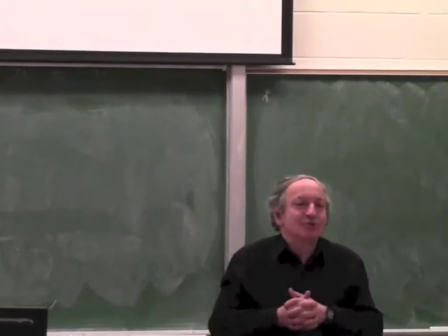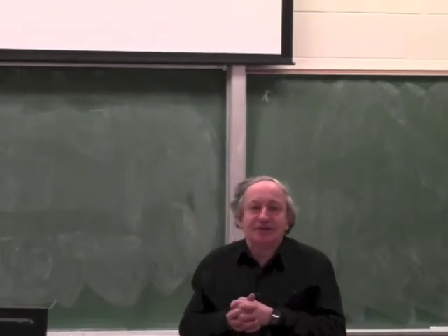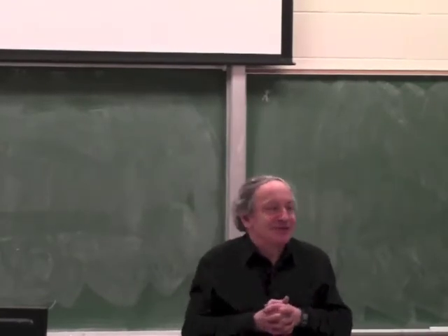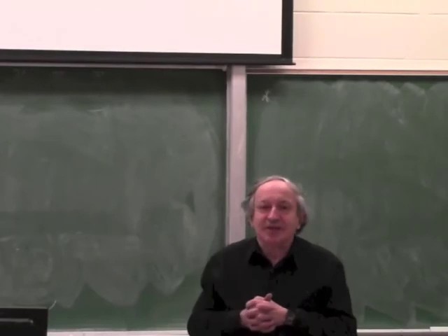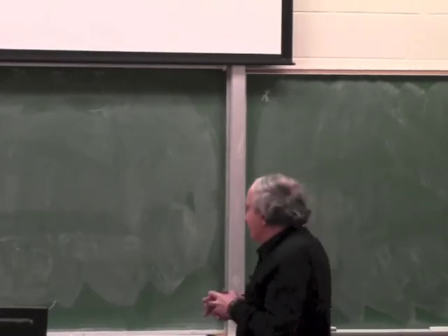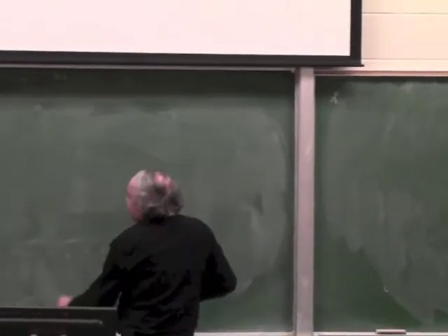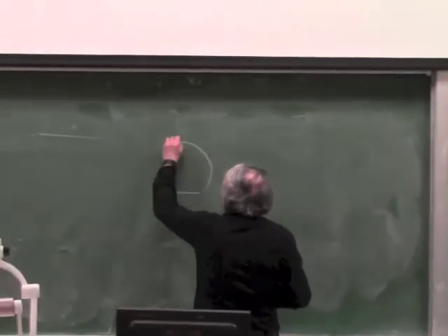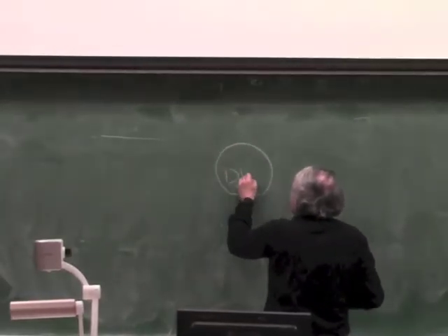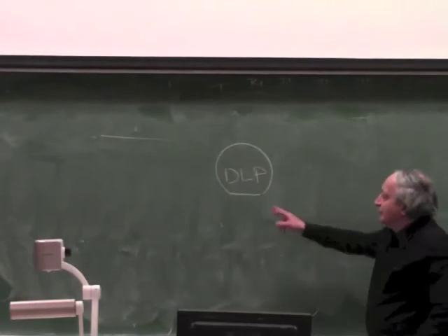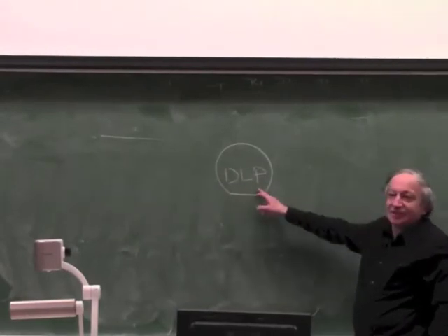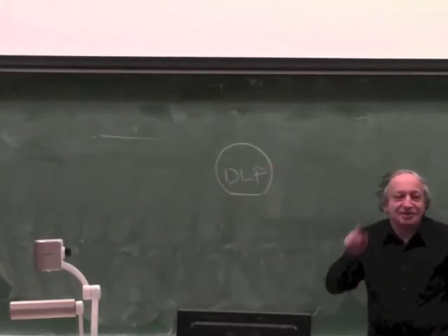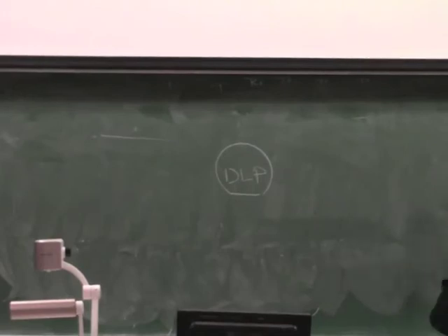So this is the most popular application today of electrostatic actuators. It was developed by Texas Instruments, and they call it DLP. When you see some projectors, they have this logo on them, and it says DLP, which stands for Digital Light Processing. So when you see this logo, it means this projector has 1 million electrostatic actuators.